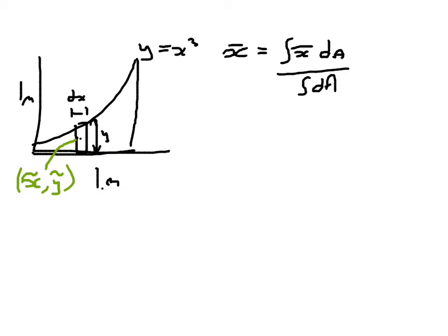And we know that the y coordinate, y tilde, is going to be y over 2, because it's halfway up that strip. So if that's y, the centroid position of just that strip that we're breaking our shape into when we integrate will be y over 2, just there. So what we now need to do is take the three terms from our equation and start putting them together. That should be x tilde, sorry.